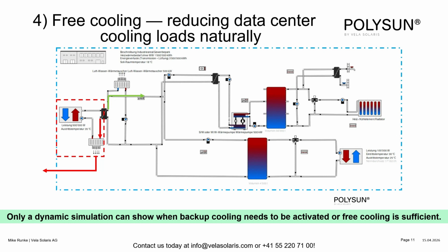A significant added value is created by plant simulation. Only with dynamic simulation can you determine exactly how many hours of free cooling are truly usable and how storage, heat pumps, and bypass systems can be optimally dimensioned. That we have seen in the simulation analysis, where we can check each timestamp of the year, what is going to happen with my system and does it function as I wanted it to.